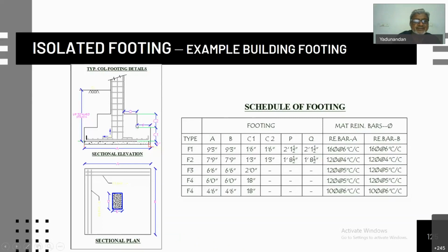The old style of providing tapered footings is not encouraged at all, and you should use stepped footing, because you have to cast the footing within formwork to get the maximum confinement of the reinforcement and provide the details selected.